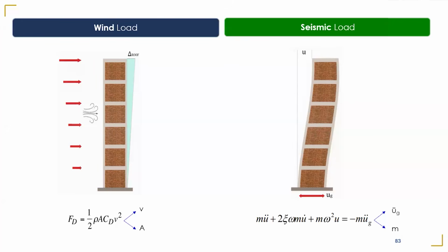For the wind, same thing. Wind is coming, but how we position the structure, how we design the form and shape of the structure, and so on, so that we minimize both along-wind and crosswind response, balance them. So the structure's form and properties are now going to affect the load. They are not independent of the structure. So it's a load and structure interaction kind of a thing. And this doesn't happen for low-rise buildings. This mostly will happen for high-rise buildings. For earthquake, yes, we can still use it for the low-rise building also.